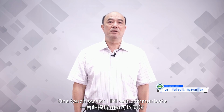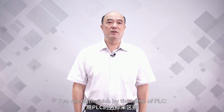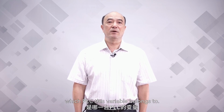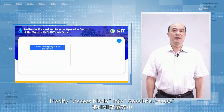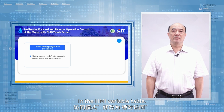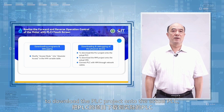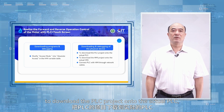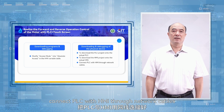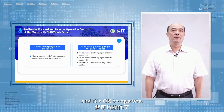One touchscreen HMI can communicate with several PLCs at the same time. You can distinguish by the name of PLC which PLC this variable belongs to. Modify access mode into absolute access in the HMI variable table. Downloading and debugging of the physical device: to download the PLC project onto the actual PLC, to download the HMI project onto the actual HMI, connect PLC with HMI through network cables, and it's okay to operate.